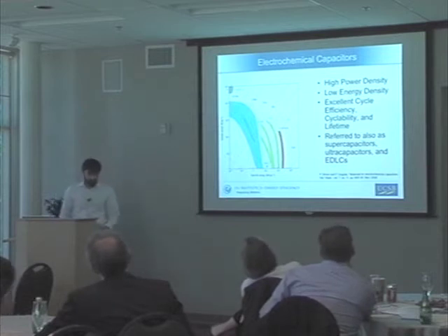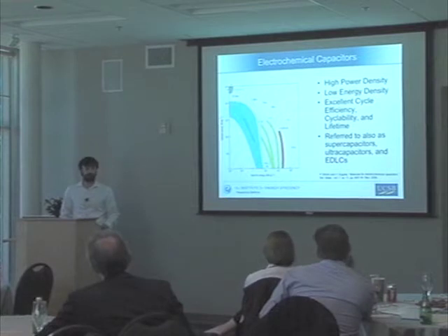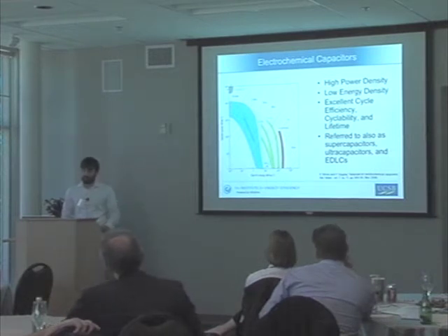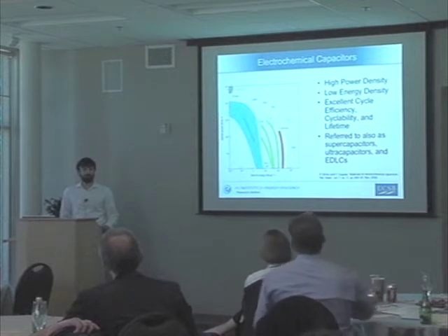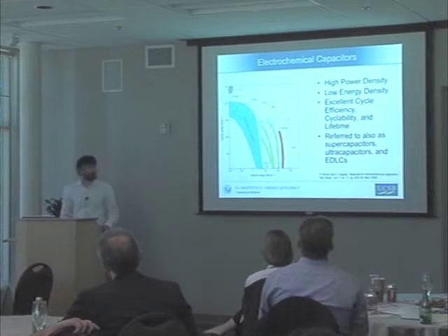One example I think is really useful to illustrate the importance of specific power is regenerative braking in automobiles, which is an emerging field. When you are moving at high speed on the highway, you have a large amount of kinetic energy which you waste as heat when you apply your brake pads to the calipers in your wheels. If you have a hybrid or a fully electric automobile, instead of wasting this energy as heat, you can drive your electric motor in reverse, because an electric motor driven in reverse is a generator, and this can store electrical energy back up for your next acceleration period.